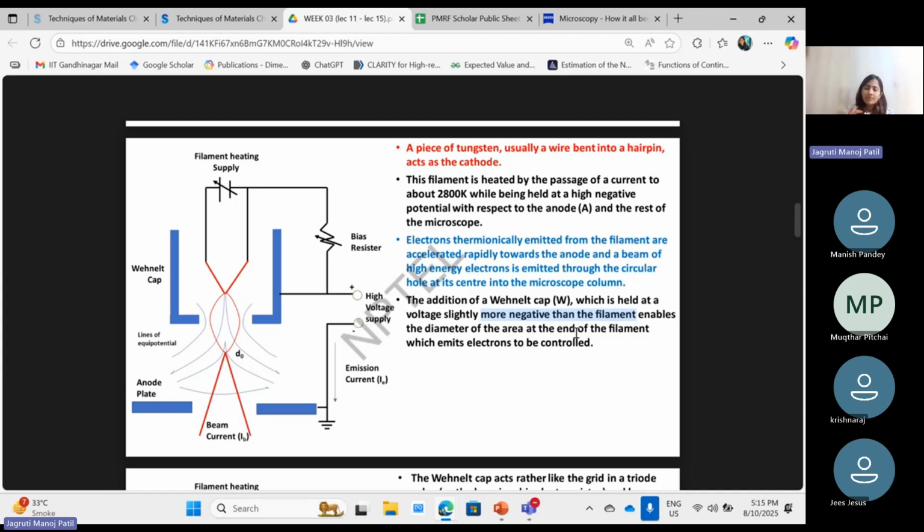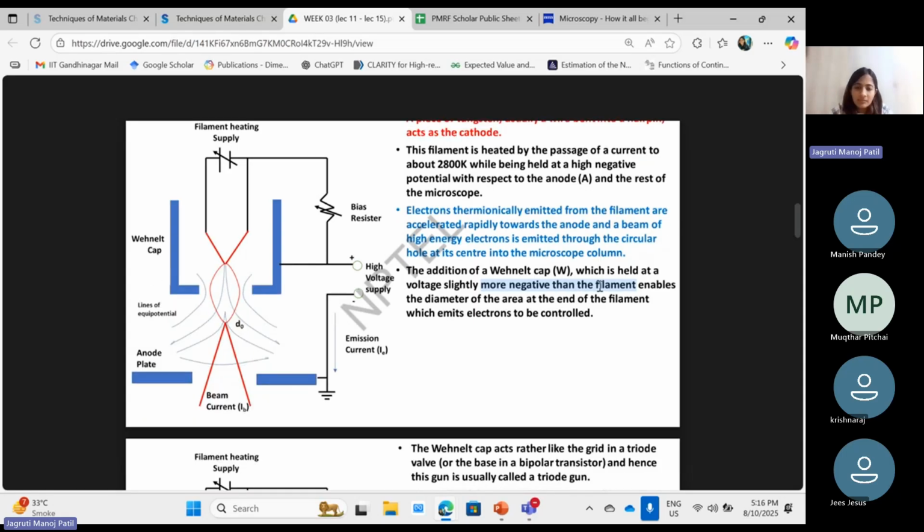In some cases, if our sample is not conductive enough, all our electrons get deposited at one point. That's something called charging of the sample. We don't want something like that to happen. Hence, a proper ground is very necessary in an electron microscope system. Also, we don't want a higher number of electrons getting deposited at a particular time in a particular sample area, hence these numbers are adjusted in the same manner.